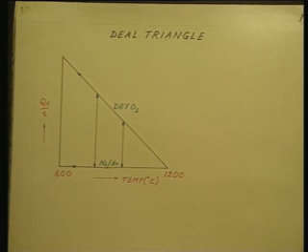What can be done in order to stop this incomplete oxidation process? Well, what is done is this, that at the end of the oxidation process, that is for the stipulated period of time you carry out the oxidation, at the end of this period close the oxygen gas flow and create an inert ambient, that is nitrogen or argon, and now reduce the temperature in this inert ambient.